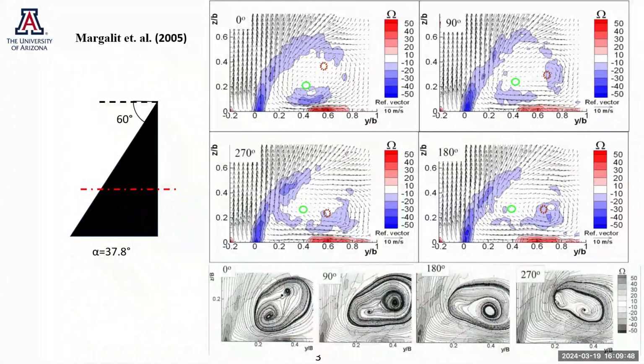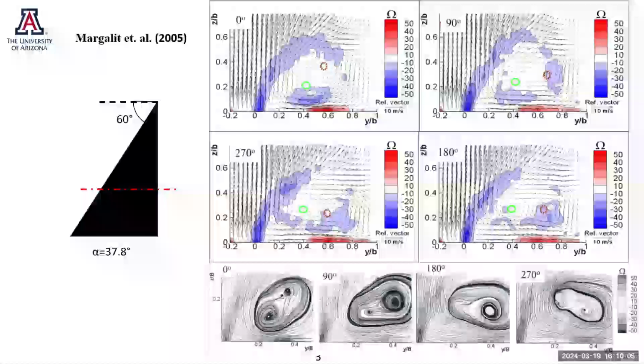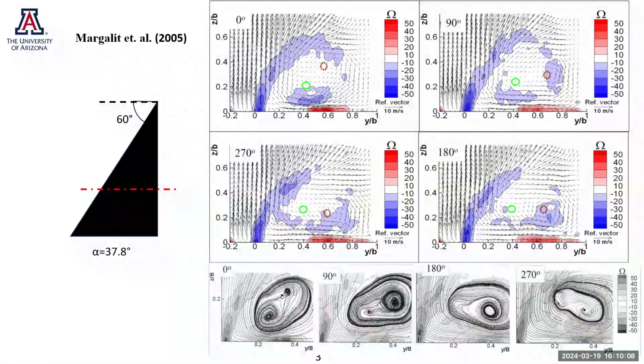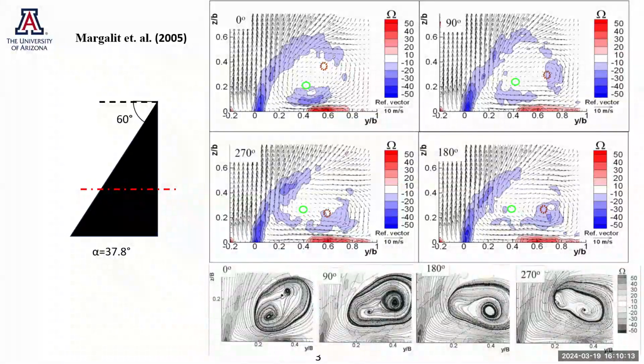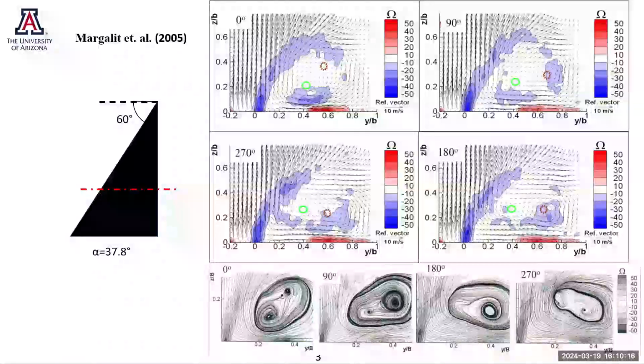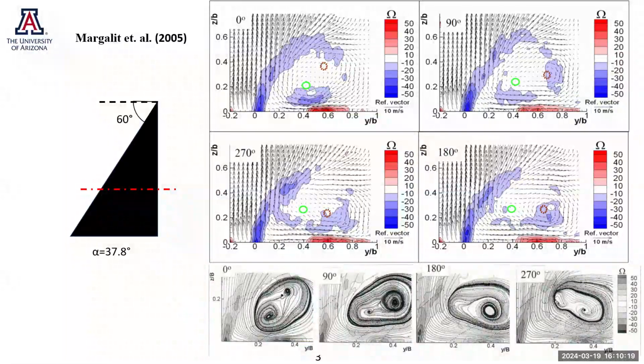You can see two locations of the center of the vortex. As you go through the phase progression, you can see how these two vortices are rotating around each other and also interchanging vorticity. At some point, like here at 270, you can see that the strength of the individual vortices has reduced. This could be because the vorticity in this plane may have convected streamwise downstream, so we are no longer recording it. But from here, you can see that there are discrete vortices which go around each other and form this vortical structure on a delta wing, which we call the leading edge vortex.